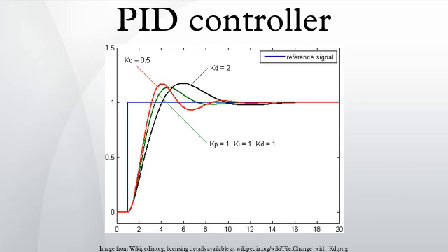Variable voltages may be applied by the time proportioning form of pulse width modulation. A cycle time is fixed, and variation is achieved by varying the proportion of the time during this cycle that the controller outputs +1 instead of 0.